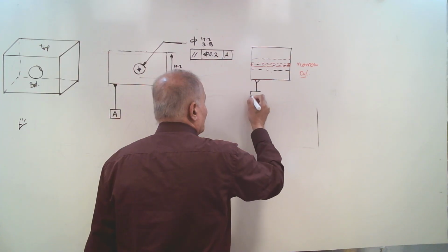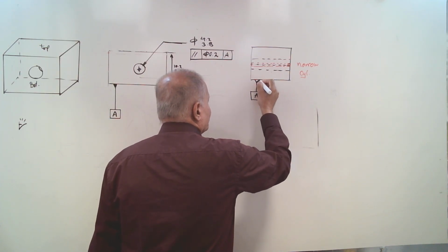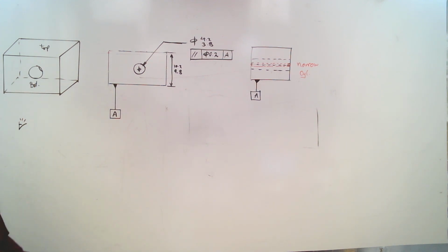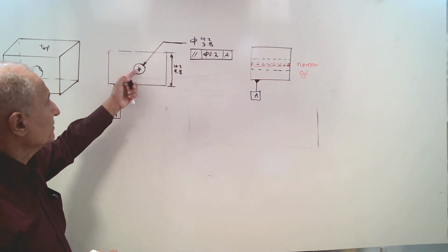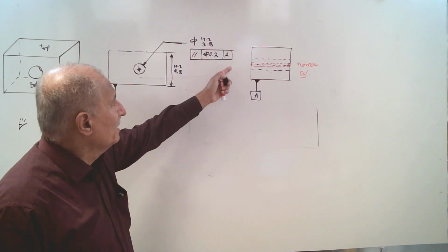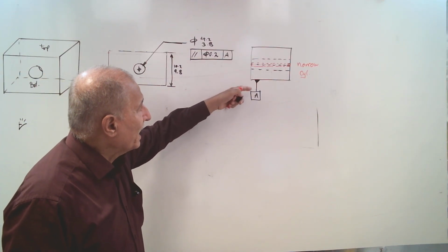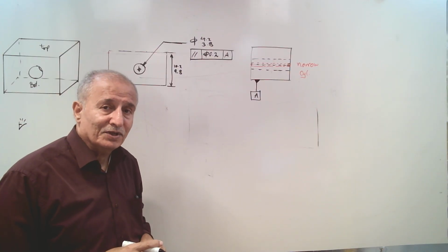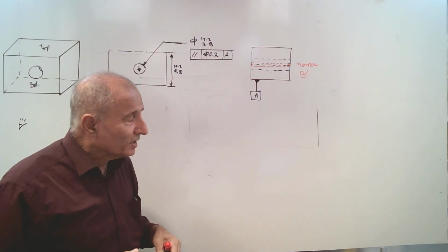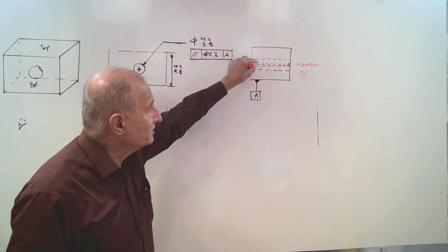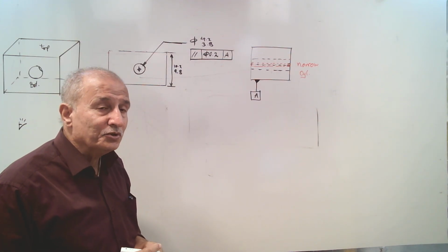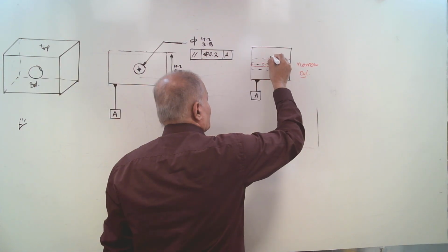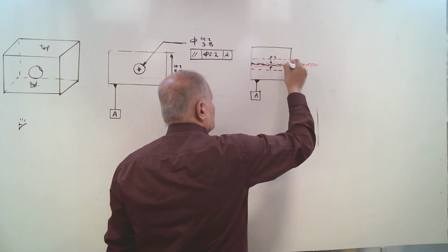I can show the datum here as well. The base can be filled or unfilled. Both are accepted. Then it means that the axis of this hole or cylindrical object must be parallel to datum A with 0.2 parallelism tolerance or 0.2 parallelism error. It means that the size of this narrow cylinder is 0.2. And the axis must lie within that, like this one. Assume that this is the axis.